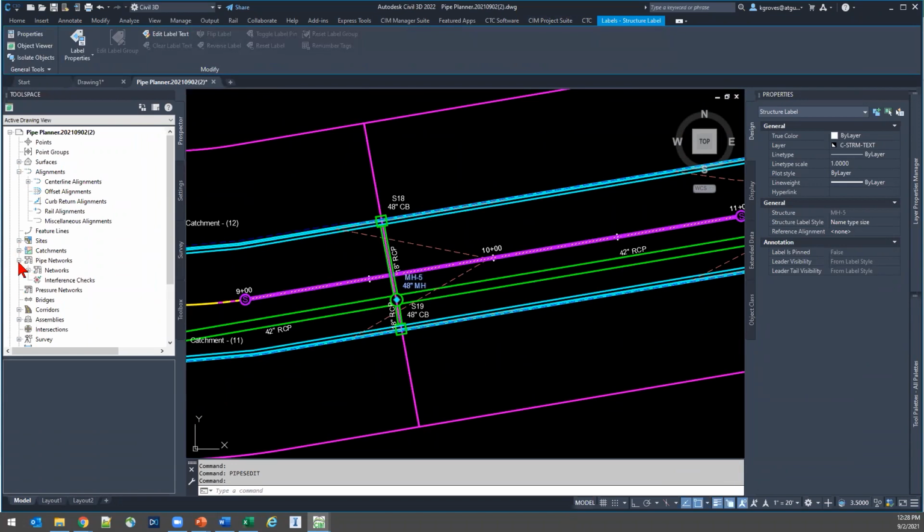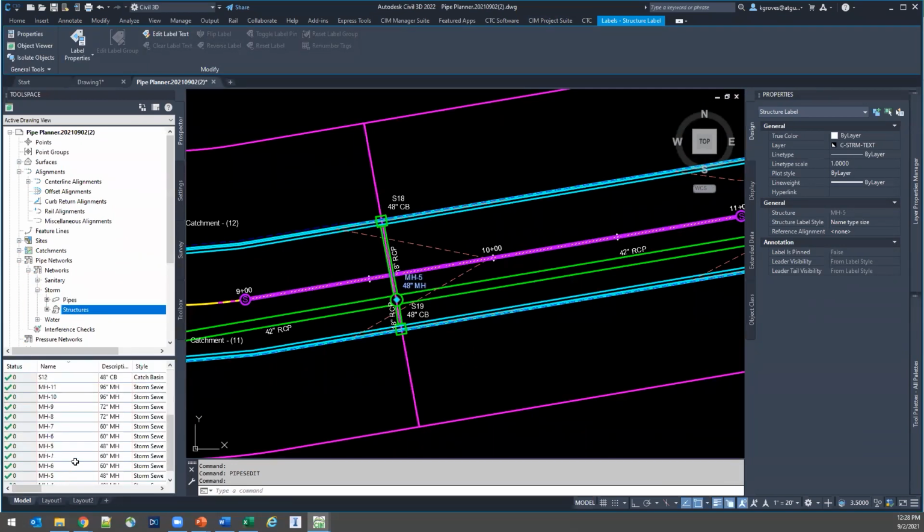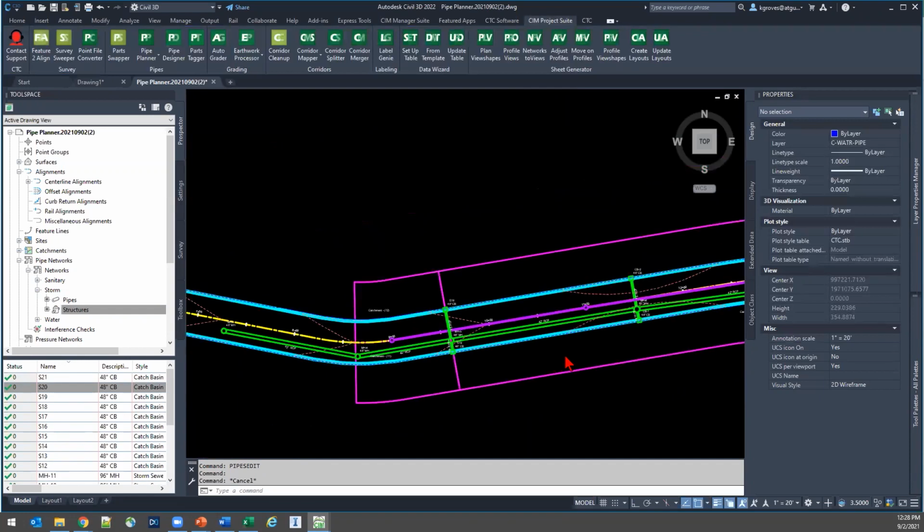My prospector is going to show me my structures. Oh, I think the equal sign was throwing it off, we can't use that syntax as part of our names. Catch basins 1 and 2 made their changes. Manholes, all the manholes kept theirs, but that equal sign did not work so great for the rest of those catch basins. So that's the type of stuff that we can do.